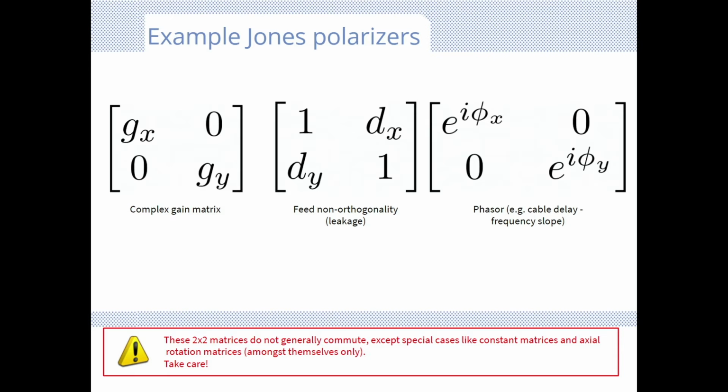You can think of an old analog system where you have a coaxial cable connecting the two antennas. There are a bit of kinks in the cable connecting to one that will induce an impedance on the measured signal with respect to the other antenna. It's important to remove that if you want to correlate those two signals together. So that is one place where we use a phasor matrix.